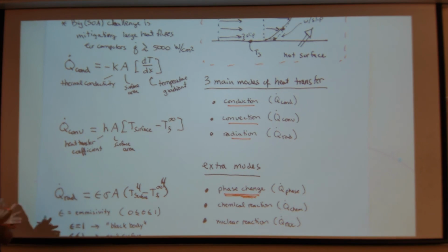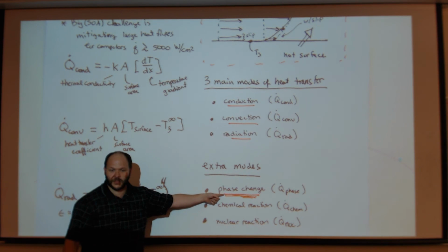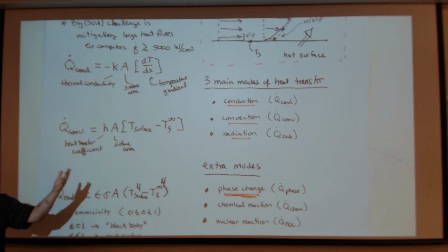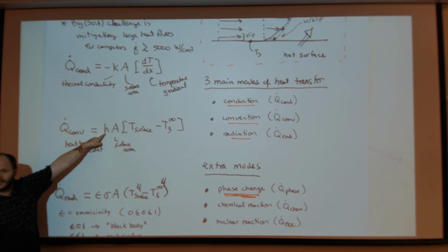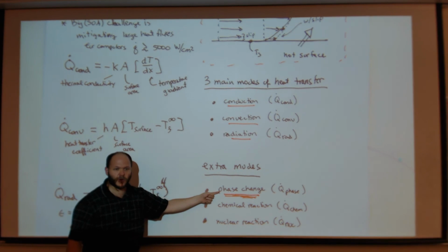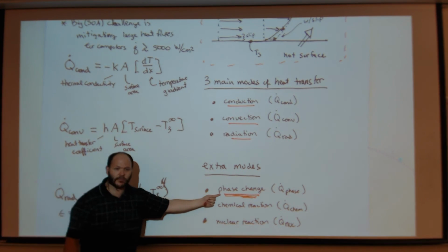I could just have pure air, and the faster you drive, the cooler it feels. But I could get my hand wet, and then I also have evaporation. I'm sweating now, so I can just do this and feel it. You can see that this heat transfer coefficient has a phase change part in it. So the heat transfer coefficient increases even more if you're having phase change.